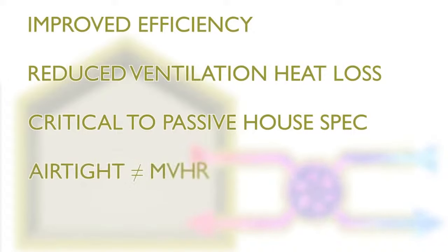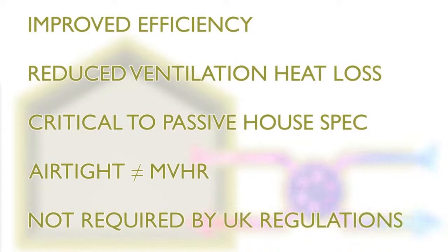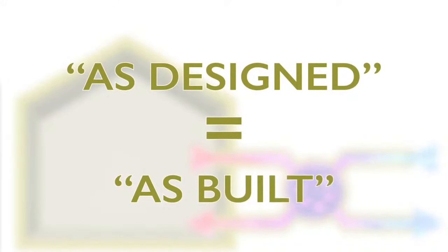This requirement in the Passivehouse specification often leads to an incorrect assumption that all airtight buildings require mechanical ventilation. If designers are not working to the Passivehouse certification specification, then various other options for both ventilation and heat recovery are available. In fact, it's perfectly possible to have good indoor air quality at low air leakage levels with a fully passive ventilation system, provided this is designed into the building early enough.